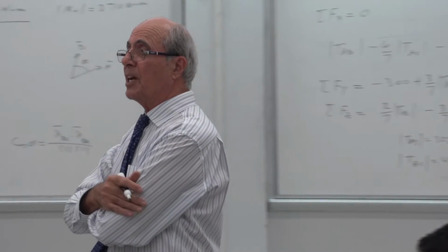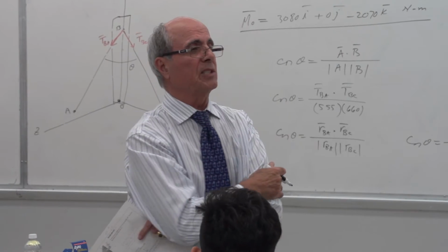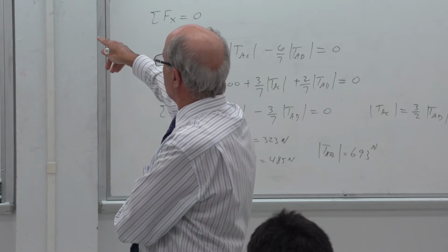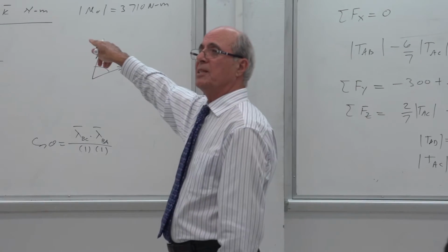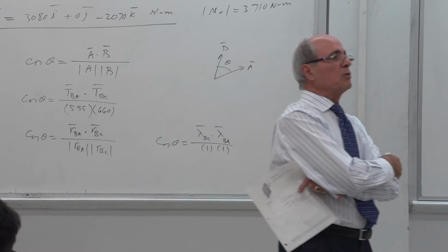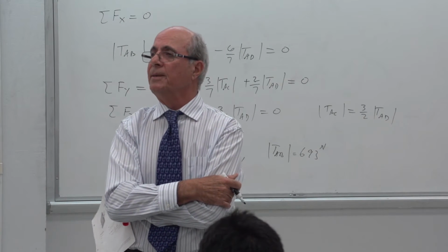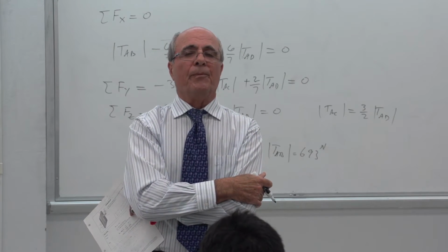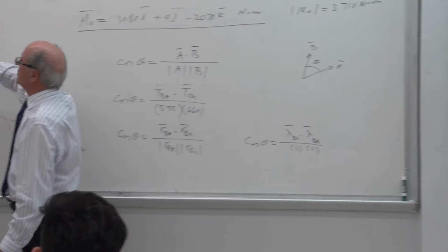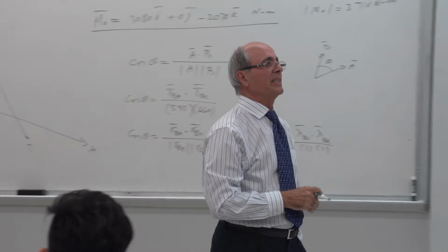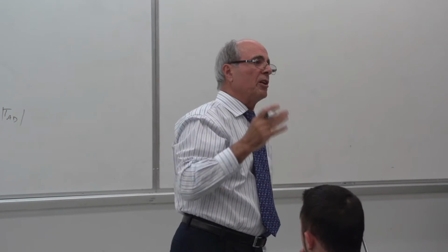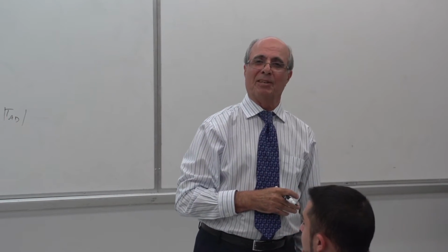FD, that's right. Because M equal to FD, that's what I hear. So if I calculate moment, like what I did here, can I use this moment? Because I have given this problem to students, and many would say this is moment, and then moment equal to FD, that's D. Is that correct or not? The magnitude? No. If I do that, this is the magnitude of the moment of both this and this about point O. Everybody understand that? If you use that, you are finding the shortest distance from point O to the resultant. Everybody understand what I'm saying?